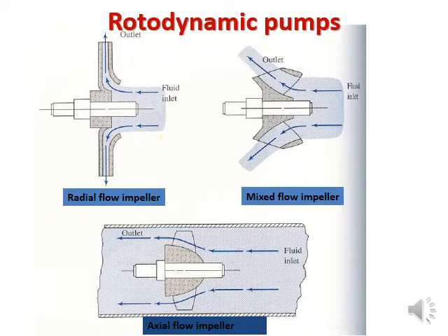See this slide carefully. This first figure shows a radial flow type pump, the impeller of a radial flow type pump, like a centrifugal pump impeller. Now here you can see the inlet is here, and this is the shaft which is coupled to drive the impeller. Fluid is sucked in and is sent out at high pressure by this rotating impeller.